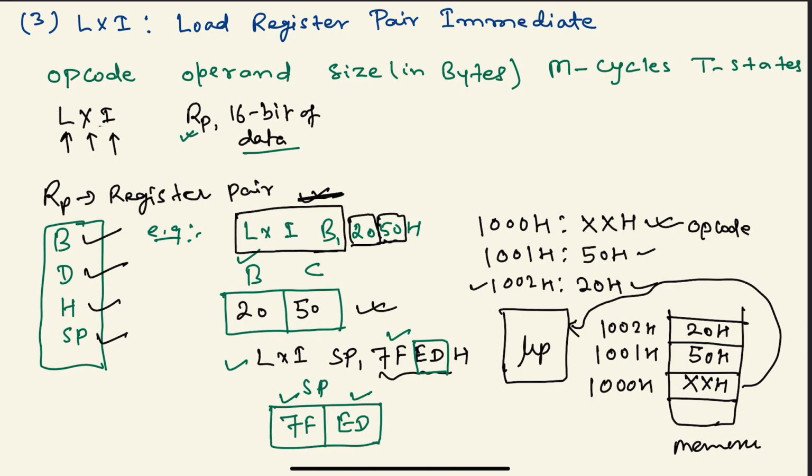So we had seen that 8085 is an 8-bit processor, so it will store only 8 bits of data at one location. So this is occupying 3 addresses here. It means it is storing 3 bytes of data for this particular instruction. So their size will be 3 bytes.